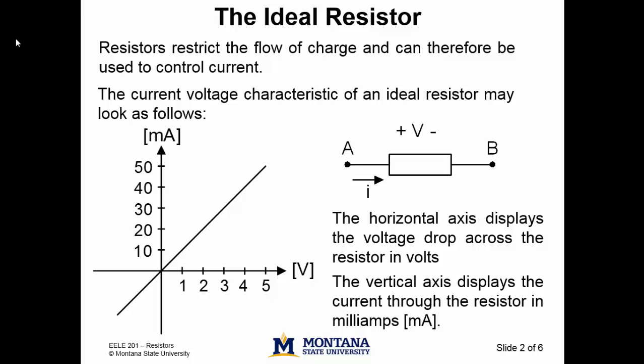Notice that when V is negative, the current is negative. Thus, flip the polarity of the voltage drop across the resistor and the current will change direction. Resistors are passive elements, and the current always travels through a resistor from higher to lower potential. Resistors always absorb power.